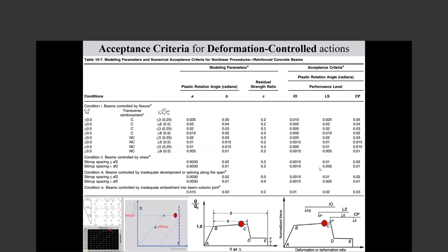For taller ones, the boundary elements are very important. Most of the ductility comes from the boundary element, but at the same time, they are very sensitive to the amount of compression in the compression part of the shear wall.